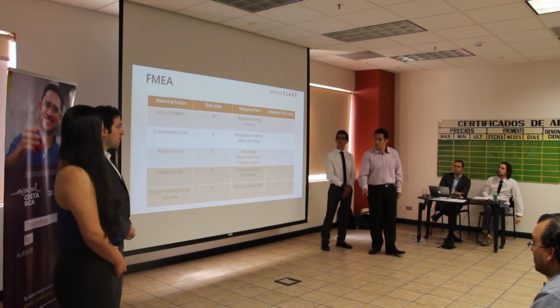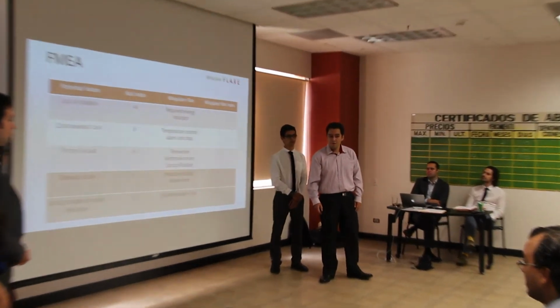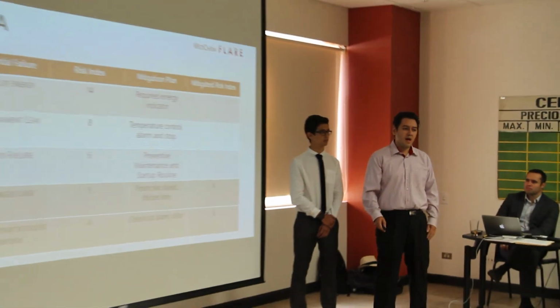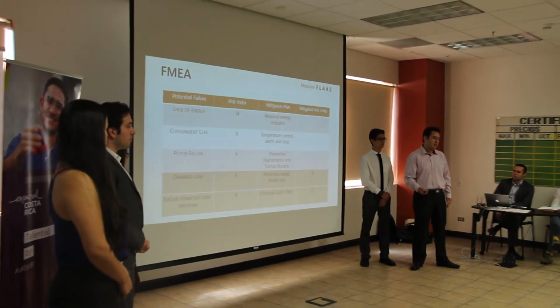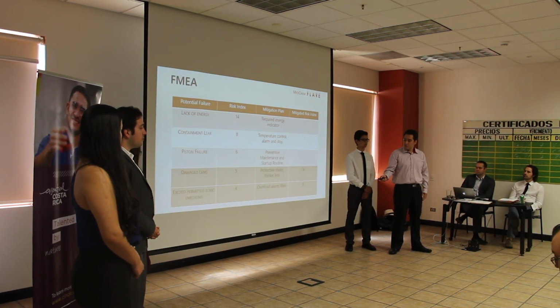Well, this is the FMEA. There are several potential failures that we have for this device. We have three that we consider are less likely to happen, but we also have to make a risk index and mitigation plans for those that are related to lack of energy, the containment leak, and piston failure that we consider are less likely. So we are going to focus on these two.